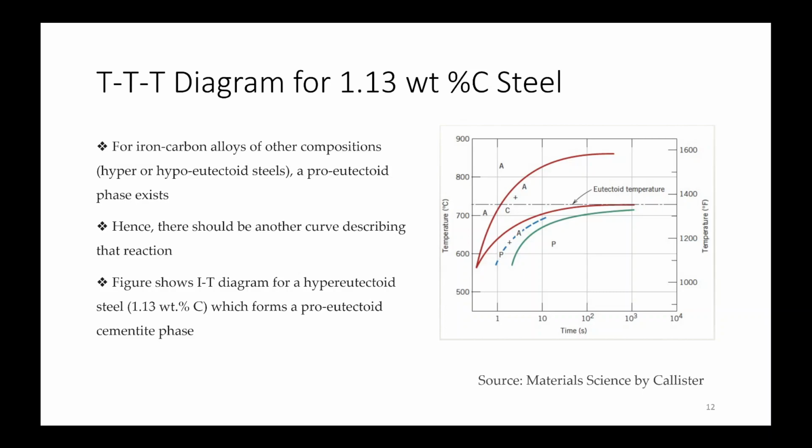It's related to what you told, right? Why do we call the iron carbide diagram an equilibrium diagram? Because if you leave your cementite at a very high temperature for a very long time, then it will break into graphite and ferrite, because graphite is a more equilibrium phase compared to cementite.